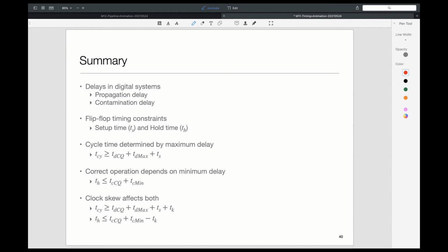So it's kind of like a top-down design flow. At the time you are designing the circuit and selecting parts, you'll have to make some assumptions about what the clock skew will be, because it's very costly to come up with the circuit components and how they're connected, then do the placement and routing on silicon, then realize something and visit back. To put it in perspective, each run through your tools may take days, right? So it's not something where I run it and, oops, it violates hold time, let me cycle back, right?